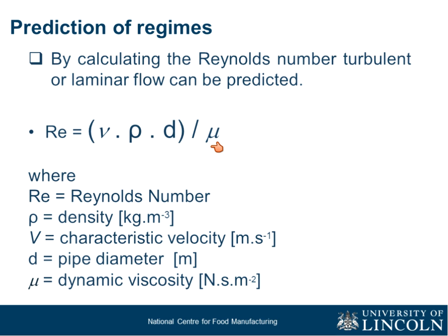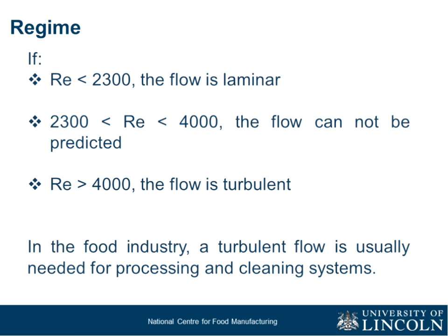These are things that you need to know about Reynolds number, and I will tell you more things that you need to know. Now, let's look at an example, because it's always good to calculate, to illustrate using an example. Look at this. If your Reynolds number is less than 2300, you need to know this number. This is laminar.